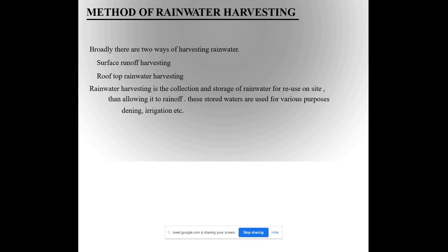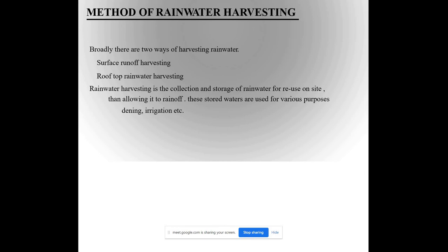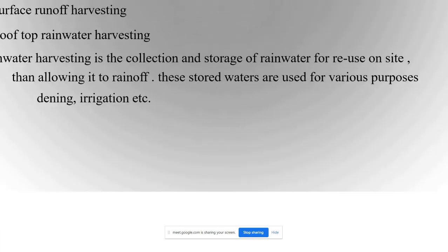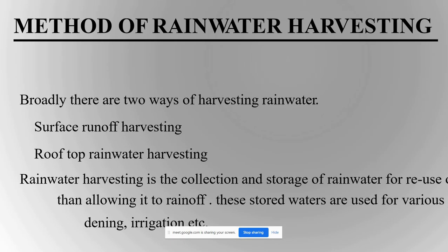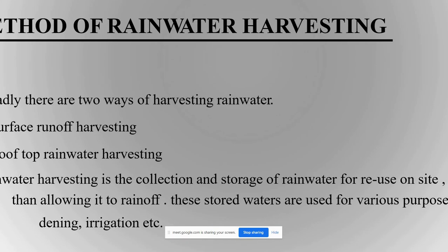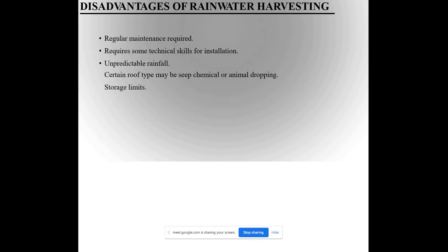The components of rooftop rainwater harvesting. The system mainly constitutes the following subcomponents. First one is catchment, second one is transportation, third is first flush, fourth is filter. There is always some skepticism regarding rooftop rainwater harvesting since doubts are raised that rainwater may contaminate groundwater. There is a remote possibility of this fear coming true if the proper filter mechanism is not adopted. A typical photograph of a filter is shown. There are different types of filters in practice, but the basic function is to purify water.